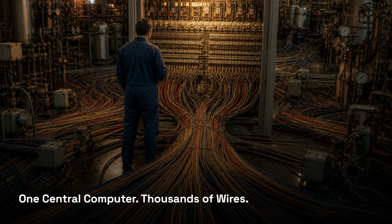Early industrial control systems placed all the control hardware in one room. Wires ran hundreds of meters to every sensor and valve across the plant. If that central computer failed, everything stopped. If a wire corroded at the far end of the facility, the whole loop went down. Engineers needed a better architecture.